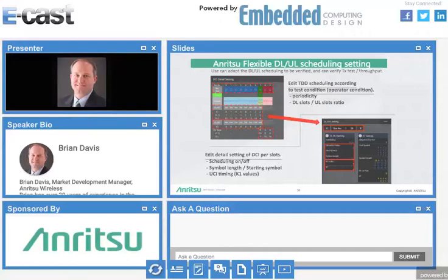We can also change in TDD. You can edit uplink and downlink scheduling. This is key to detect different operators and different dynamic network conditions, because you're going to be changing your uplink and downlink slots on the fly. The network is based off of users and conditions in the network.